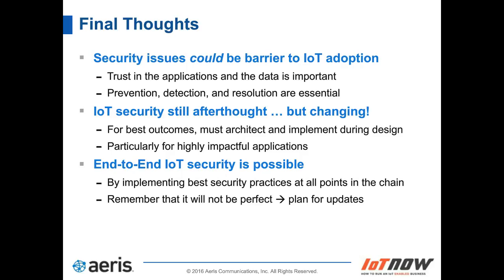One of the challenges that people always have is how do you change a device that is deployed out in the field, because if you have a tremendously large number of devices already out there, you have to perform IoT updates. And we believe that people need to take that into account and therefore implement systems that would allow the firmware of the device or the application software of the device to be changed after it's been deployed. Something we've noted is that today security is still an afterthought, but it is changing. Ideally, you must architect and implement it during the design, particularly for any application that could have a serious impact if it was breached. So I do believe that end-to-end security is possible by implementing the best known security practices at all points in the chain.